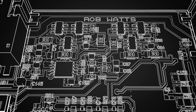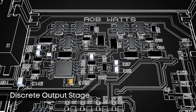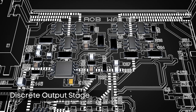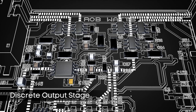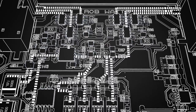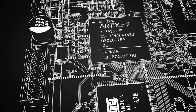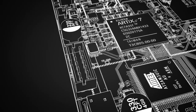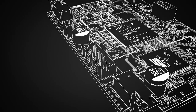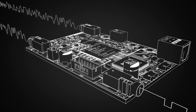Instead of using a semiconductor chip, op-amps or other active electronics, Chord uses a discrete output stage to amplify the converted analog signal directly from the flip-flops. The signal only passes through 5 individual components and helps keep the signal path very simple. Because of this, along with the fact that the volume control is handled digitally inside the FPGA without loss of information, due to Chord's unique oversampling process, there is very low small signal distortion in comparison to using active electronics or signal paths with hundreds of components.